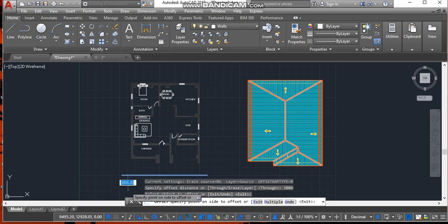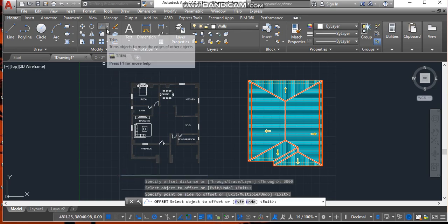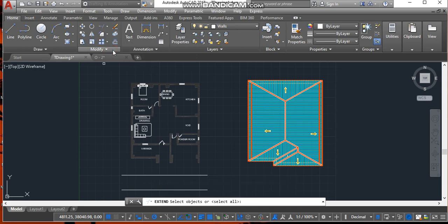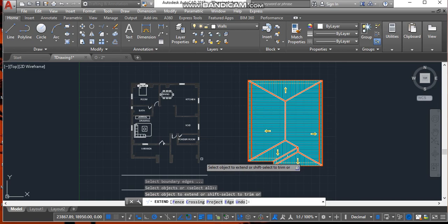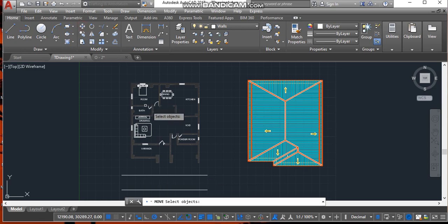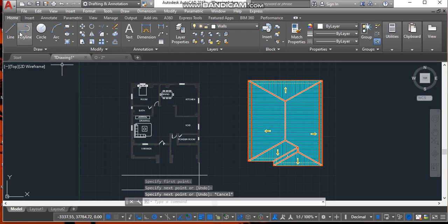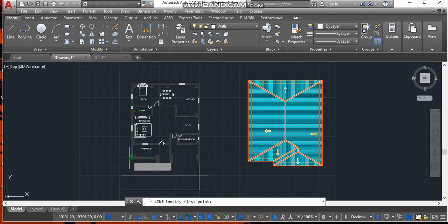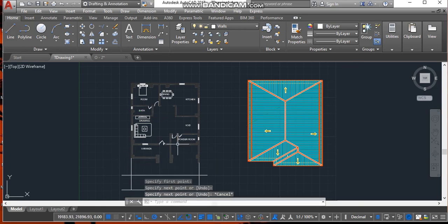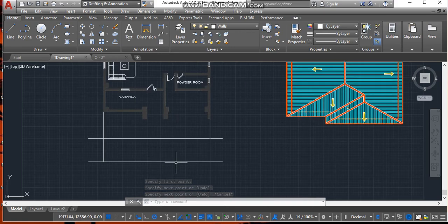Well, it depends on what your clients want and also the standard in your country or region. This is the elevation of the house, from the floor of the house to the place where the roof or the ceiling is going to be. So that is the elevation of 3000. That is the standard in my country and region, so that's what I'm going to be using here.